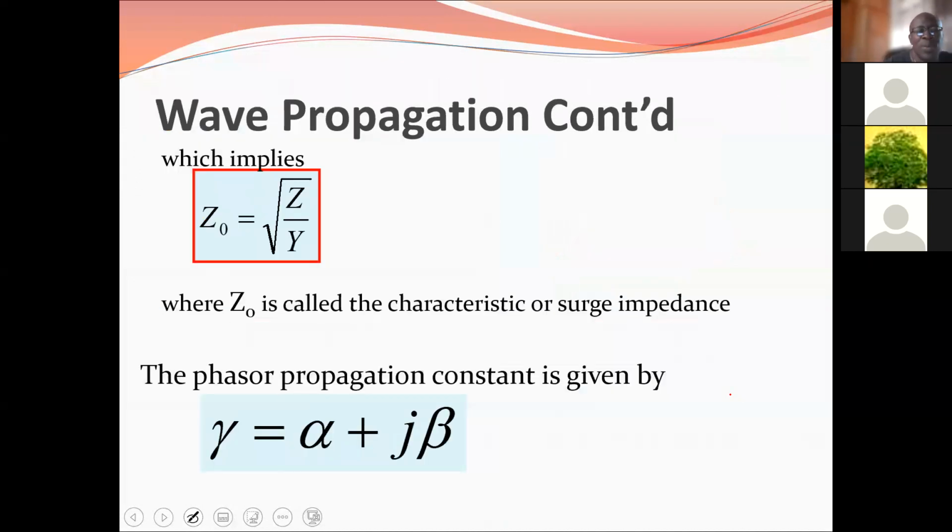We're coming to that right now. So I'm saying Z0 is your characteristic impedance, but when we, in power systems, refer to that, we call it your surge impedance. Now, you made a point about symmetry. Earlier, we said that the resistance, inductance, etc., were uniformly distributed along the line, which means, therefore, that whichever direction you're looking at, you'll be seeing the same distribution, no?